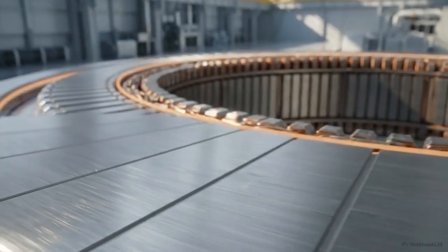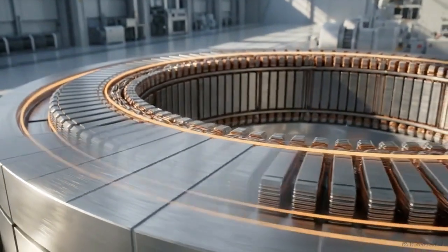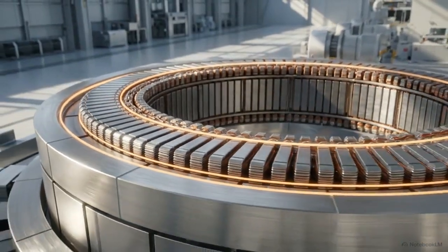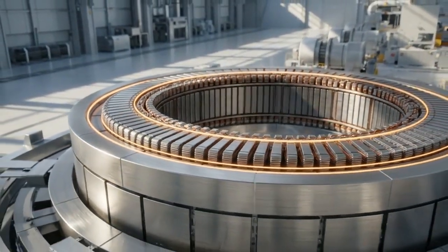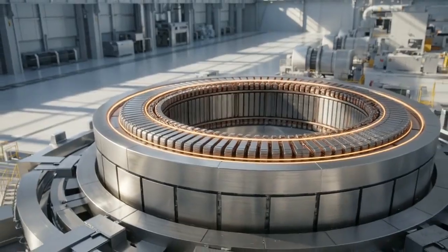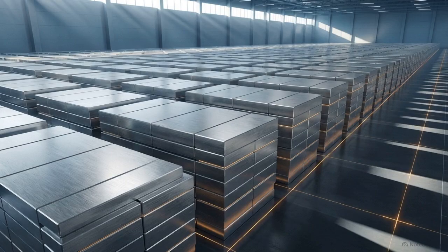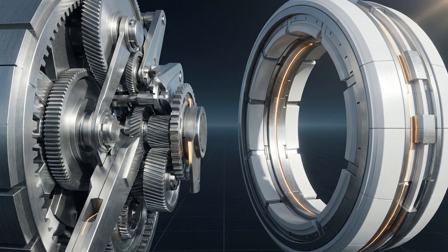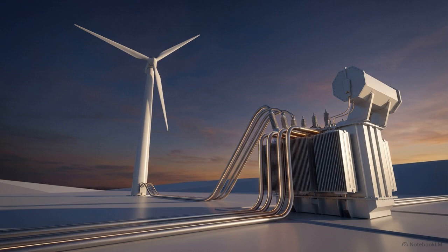Generating power at such low speeds requires a physical trade-off. The generator diameter must be expanded to accommodate a much higher number of magnetic coils. This massive scale requires hundreds of kilograms of rare earth neodymium magnets per megawatt, which significantly increases upfront material costs. Whether an operator chooses the maintenance of a gearbox or the material costs of a direct drive ring, the mechanical energy has been captured. The generator now acts as the heartbeat for the grid.